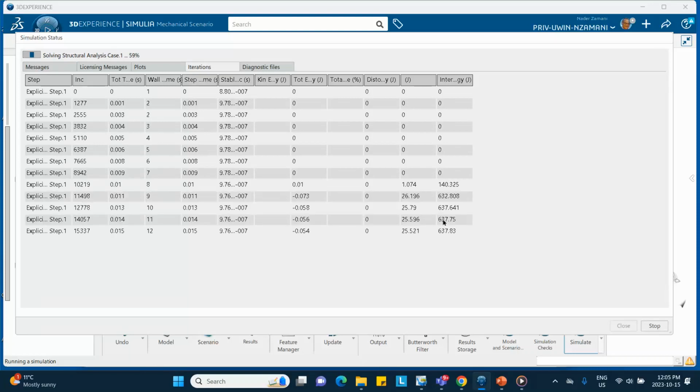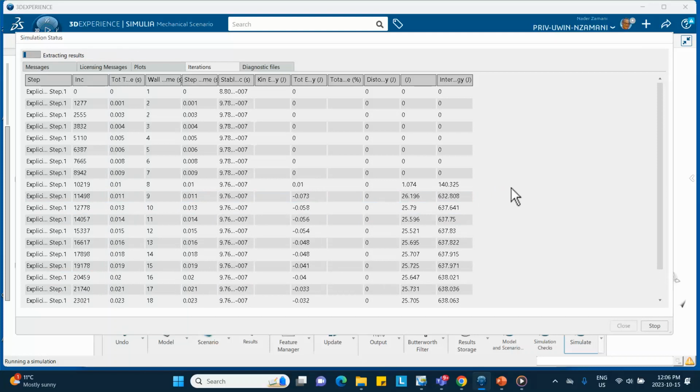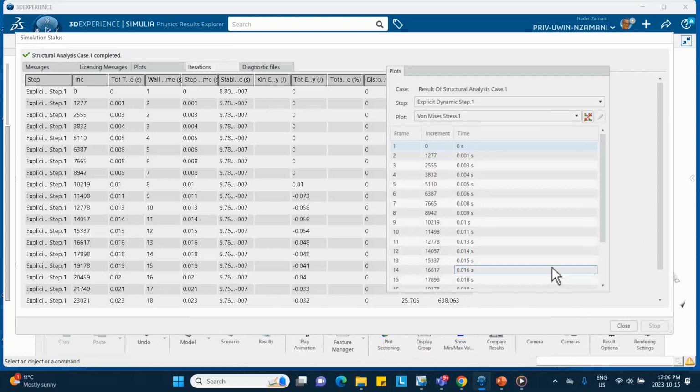I want to emphasize again, not every problem can be done with analytical rigid surface. I just showed you the case that even a sphere, if you make it as a primitive, is not going to be solvable with analytical. Analytical rigid surface must meet those limitations. Okay, this is done. Limitations are either it should have been created from an extrusion or from revolving about a particular axis.